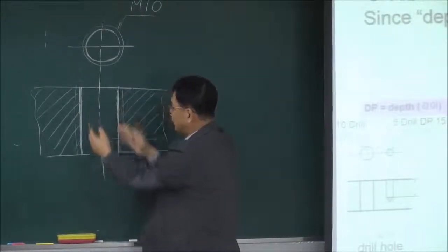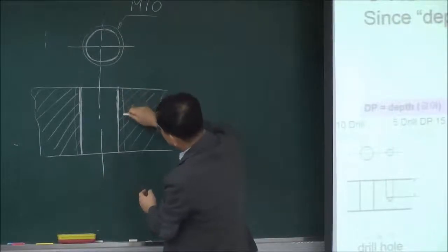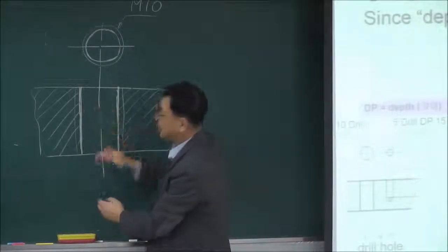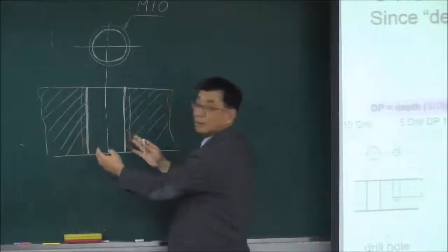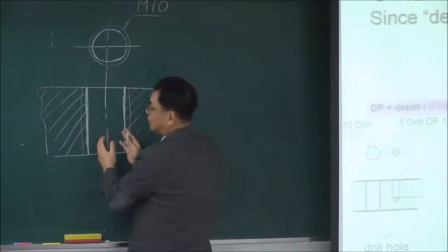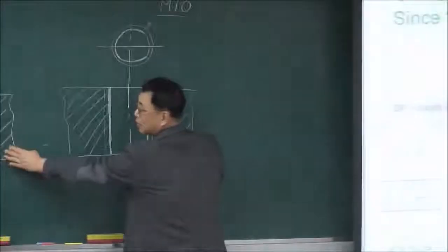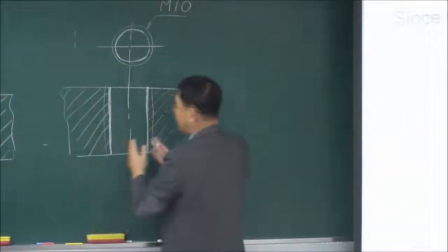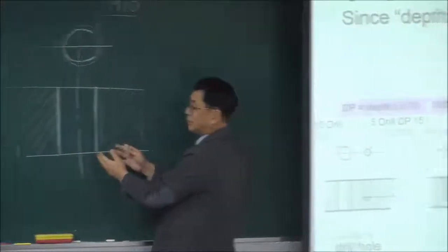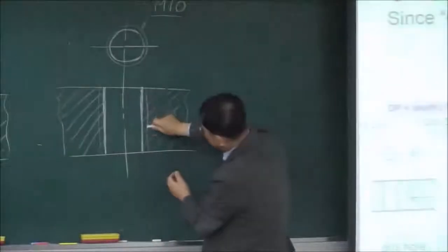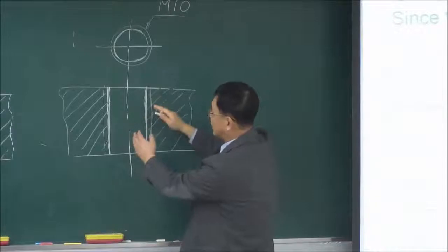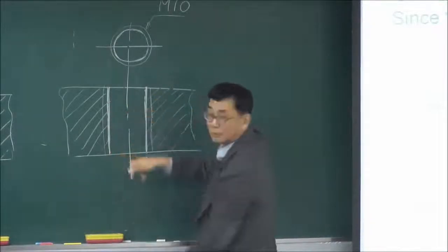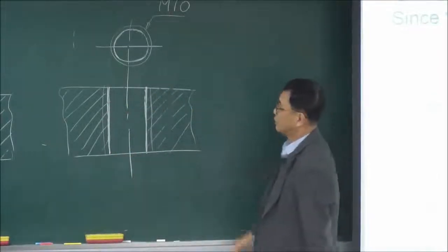The thin line represents the thread inside. So this is the abbreviation of this perfect drawing. It means that thread is machined inside the hole. This is tapping.